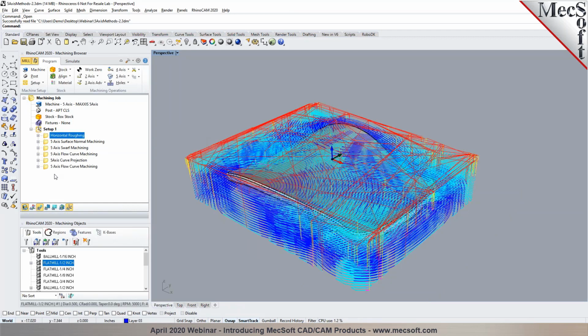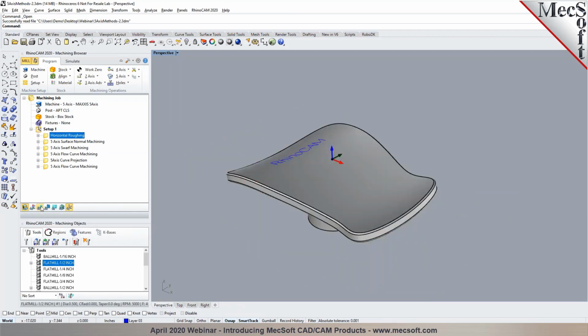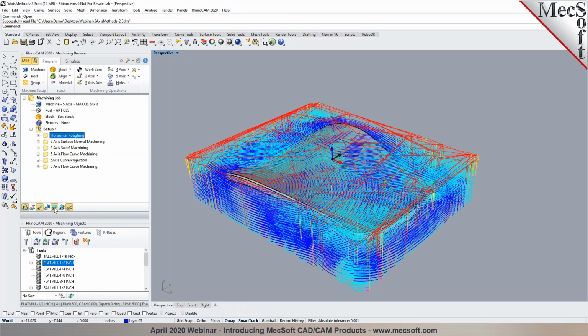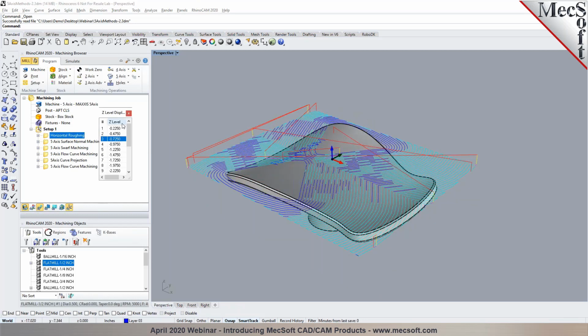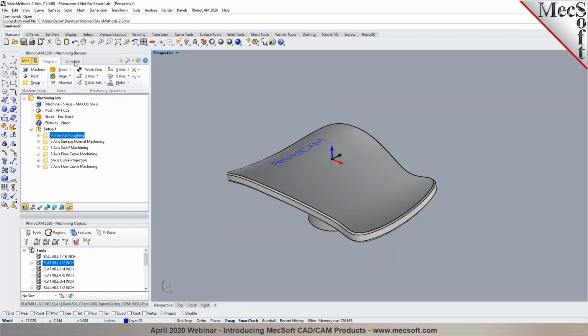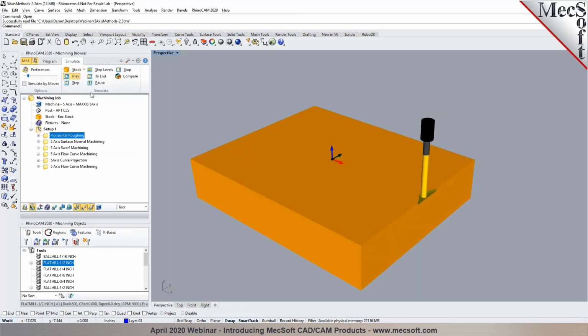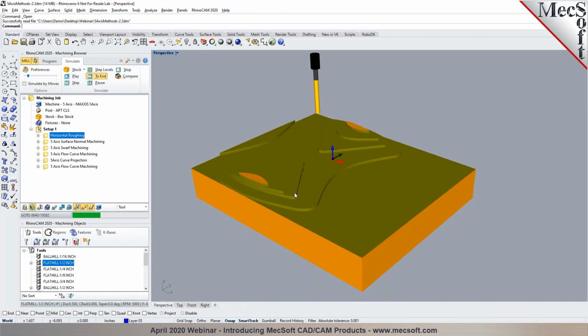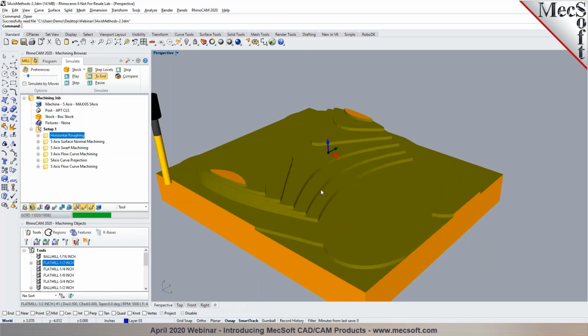So what I have here is a roughing operation that's programmed. That would typically be a Z-level roughing or a horizontal roughing toolpath. And you can program it from multiple orientations, so you can have it indexed. So you can rough it out from different orientations. I'm going to quickly run through the simulation of the roughing toolpath so we could take a look at some of our simultaneous 5-axis toolpath methods in here.